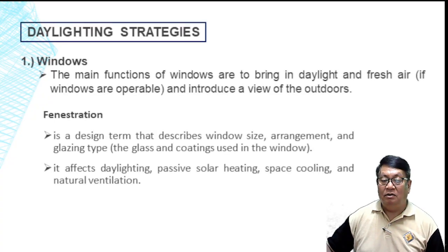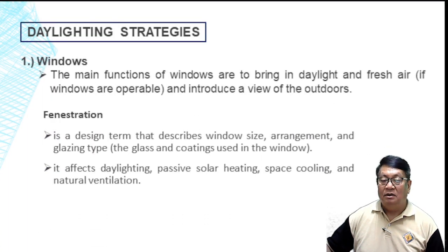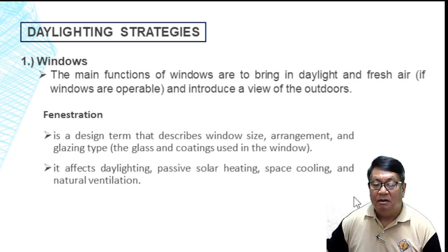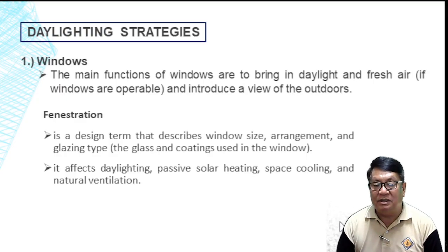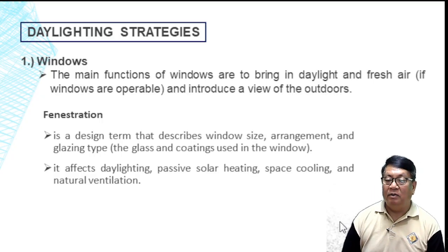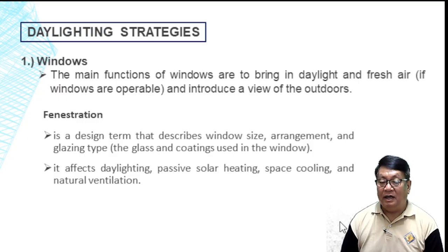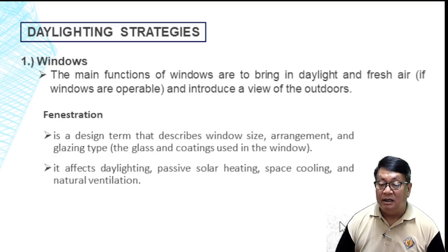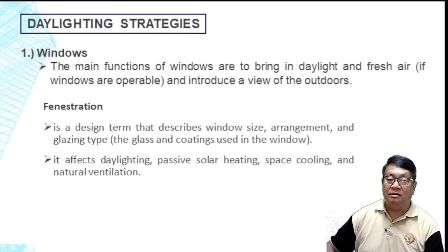Okay, so we have these strategies, no? Windows, fenestration. Okay, so try to understand what is fenestration. It is a design term that describes window size, arrangement, and glazing type. It affects daylight, passive solar heating, space cooling, and natural ventilation.